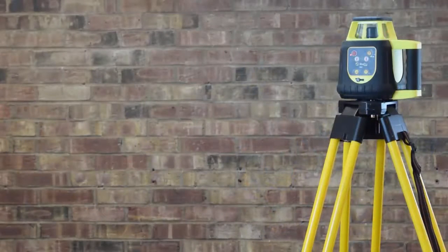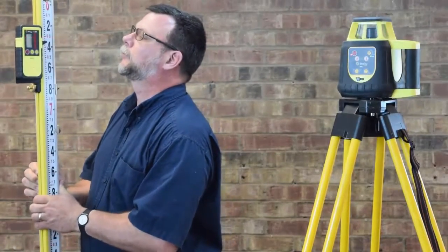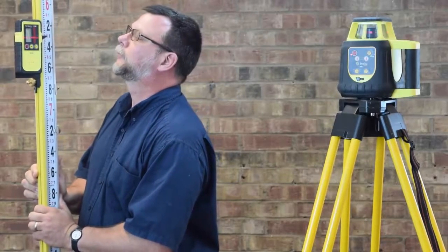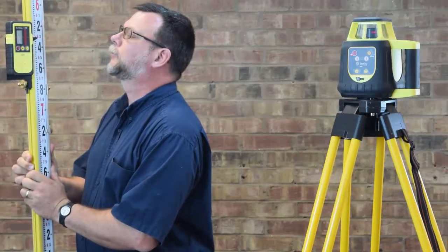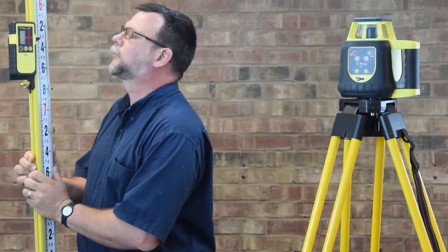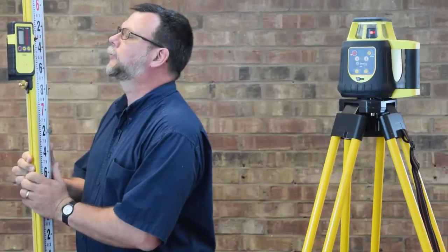With the advent of inexpensive laser devices, the rotary laser level has made some leveling surveys possible with only a single surveyor. A revolving mirror produces a horizontal plane of laser light. A laser detector on a special leveling rod enables measurement at each desired location.